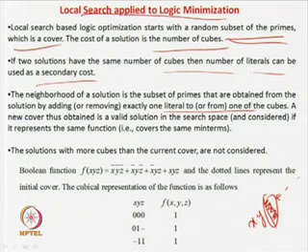When you are randomly selecting the prime implicants, your criteria should be, say initially you have taken a subset which has 10 prime implicants. Now when you are selecting another set of prime implicants, obviously the number of literals or the number of prime implicants should be lower than the one in the current solution, if you are taking that approach. But in this slide which we are presenting, we are taking a slightly different approach. In this case, we are not taking another random subset of prime implicants as the solution. Rather, from one of the cubes we are removing one literal.